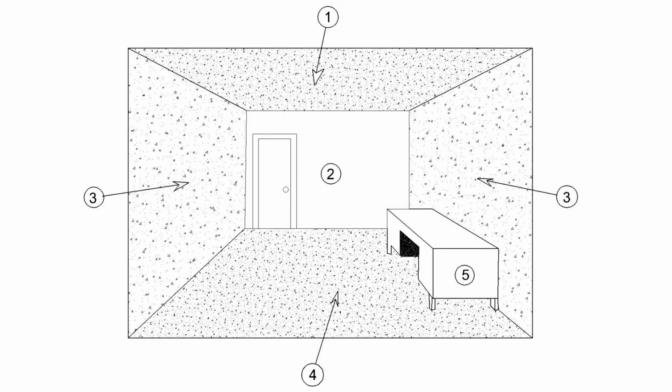Anyhow, yung color scheme strategy natin is categorized into 3. The ground, the view, and the sky. Depending on the tonal value, the land should be in the darkest, represented in our interior as flooring. Walls represent the light, which also should be in a light color. Then the ceiling represents the sky, which is the brightest color among the 3. The light-colored ceiling's function is to reflect and diffuse the light from the windows to our interiors.